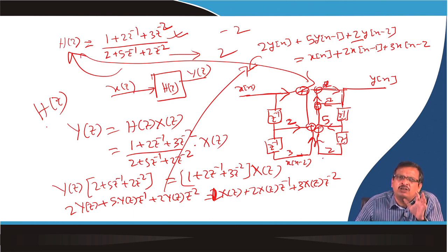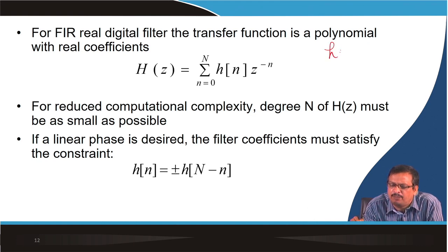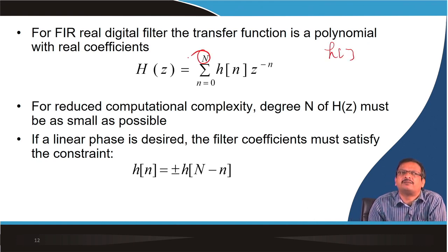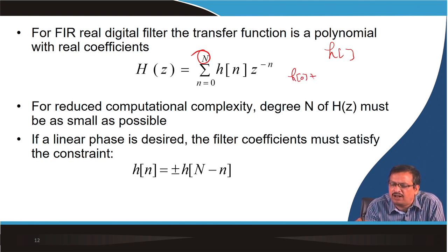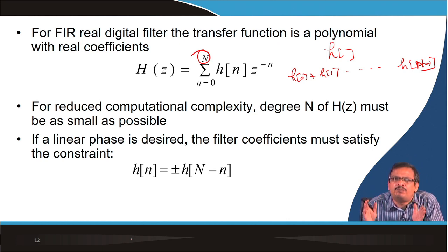There is a procedure to derive the transfer function from the given specification that we will discuss during the design of IIR filters. Now, if I truncate that frequency response, instead of infinite impulse response, let us say I take n number of impulses: h0, h1, h2, up to h(n-1), instead of infinity. So it is a finite impulse response filter.